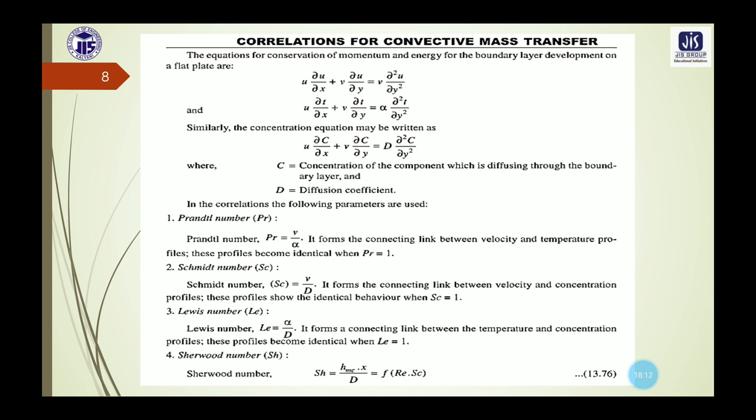These equations we have seen while discussing the Navier-Stokes equation in case of the boundary layer. Similarly, the concentration equation may be written like u ∂C/∂x plus v ∂C/∂y equals capital D ∂²C/∂y².